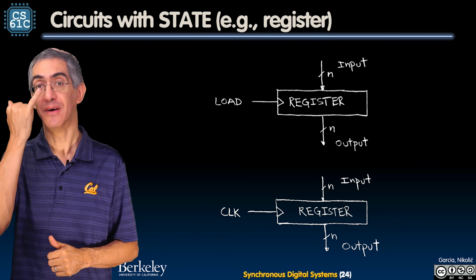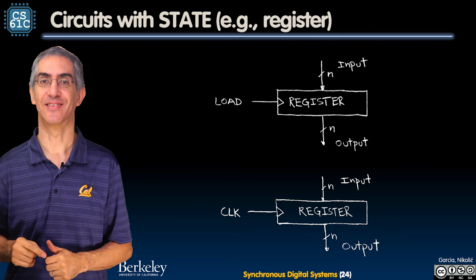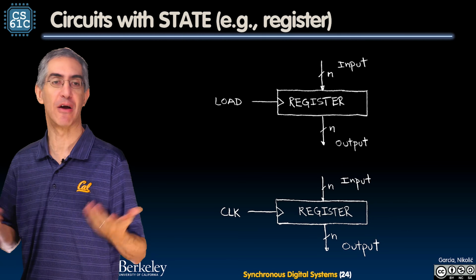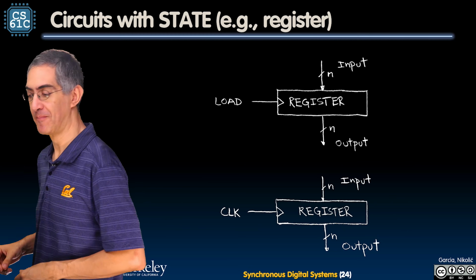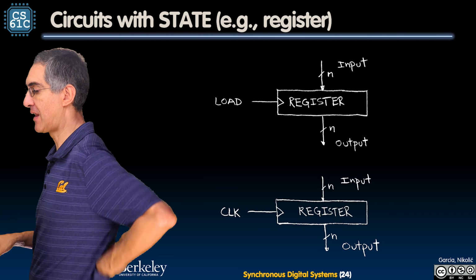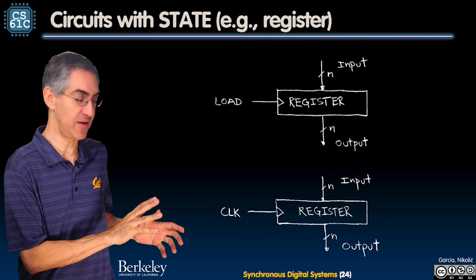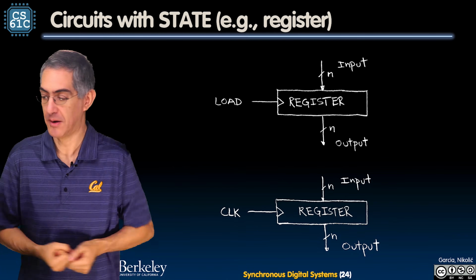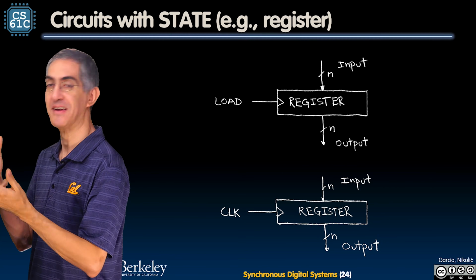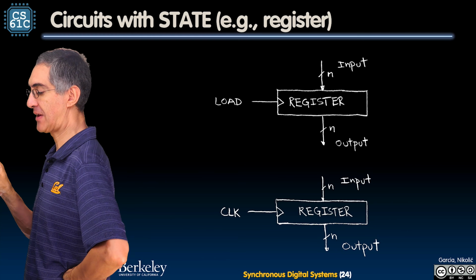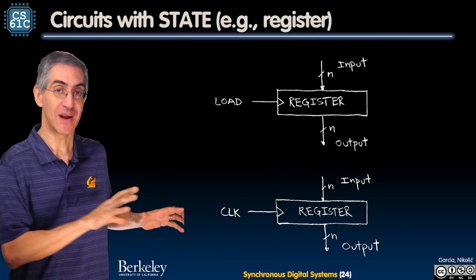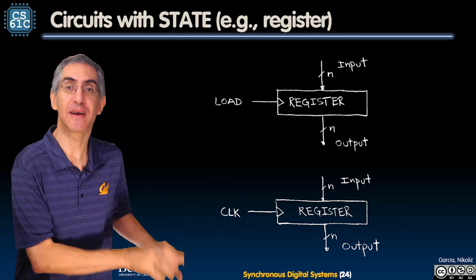What often we do is we clock these devices. So now, rather than load going up every once in a while, I'm going to go up every single clock cycle. I'm here, I got my 7, and then clock goes up, turn around, grab whatever's there. Zoop, now it's a 2. Here's my 2. I don't have 12 fingers. 2. Okay, clock goes up again, whatever it happens to be. So there's a rhythmic nature to it, okay?